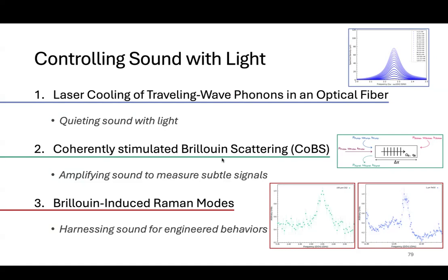They sent us primed samples with 10 nanometers of selenium as an adhesion layer, providing glue between the glass slide and the tellurium. I was thrilled. I would now be able to deposit my tellurium, have it stick to the slide, put it into the beam path of the instrument, and get that 14.4 estimated gain factor.